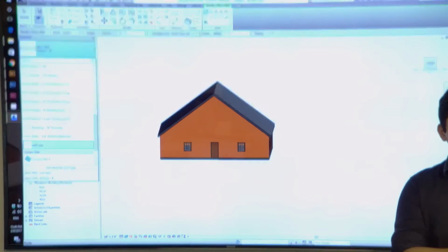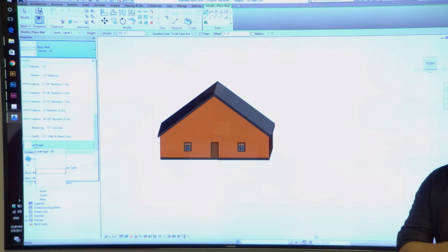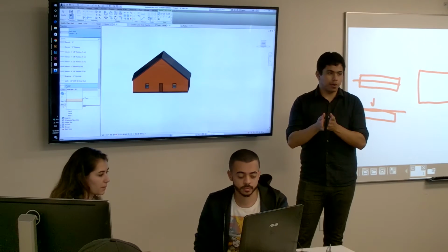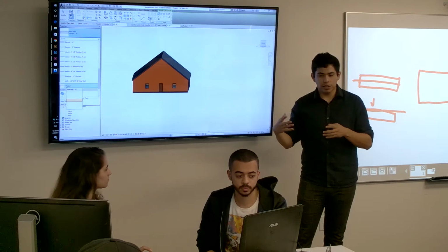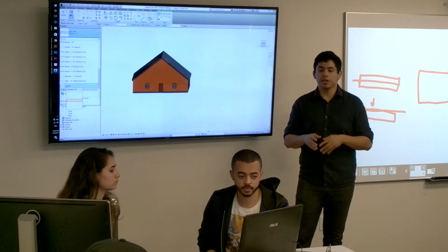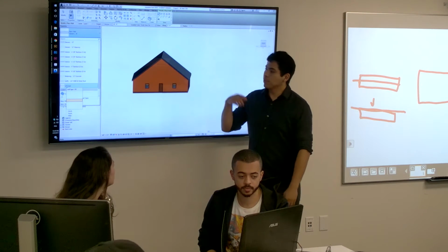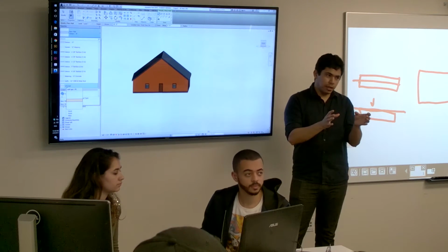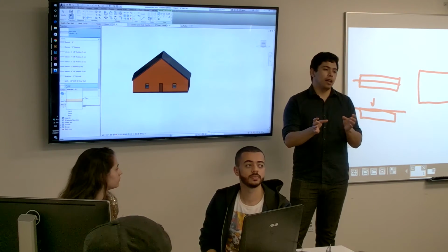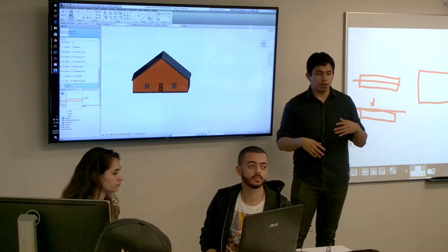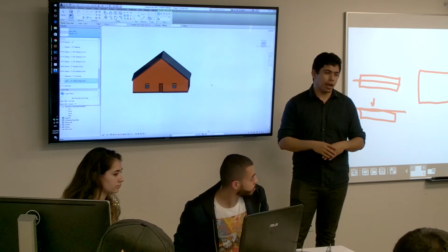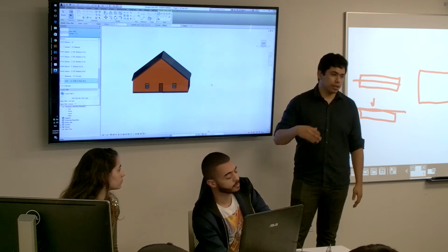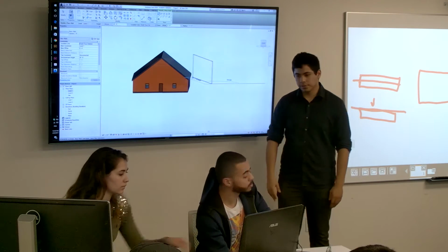They're not just walls, they're families that were built by the Revit programmers. So this is a family that you're working on, and by duplicating you're copying that family, so you have the original one and one that you're gonna modify. By all means, if you want to, work on the one that they gave you, but I would not recommend it because it's a good, quick filler that you can modify whenever you want.